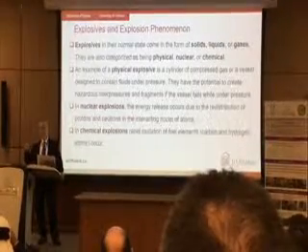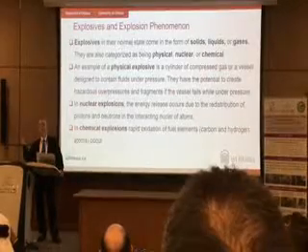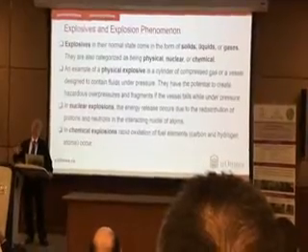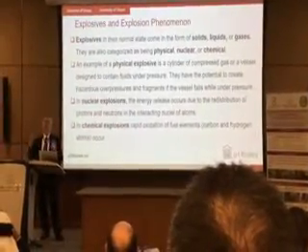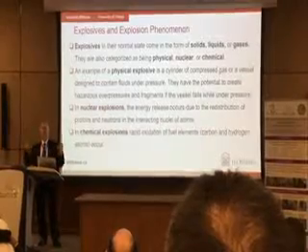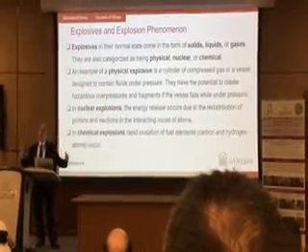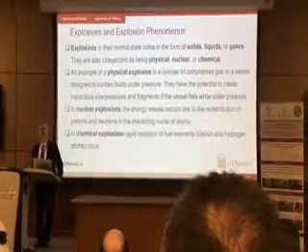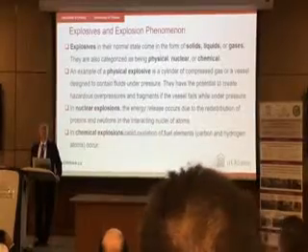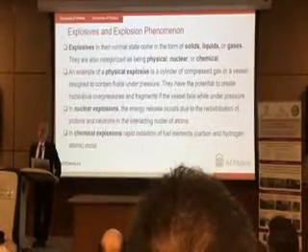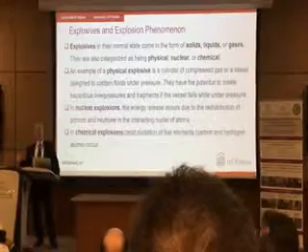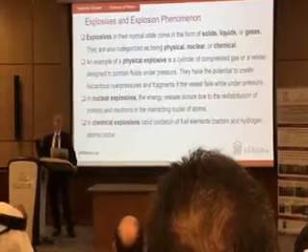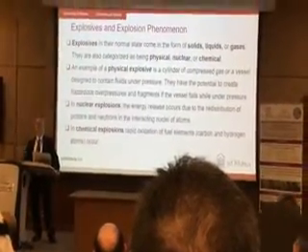Chemical explosions occur when the chemical material of the explosive is oxidized, which means it's burned inside, and it creates tremendous energy, which then translates into shock waves, and these shock waves move towards the building. And I'll show you examples of building loading. But this happens at a very high supersonic velocity. Okay, so chemical explosions are measured in milliseconds. We have 5 milliseconds to 50 milliseconds, depending on the standoff distance.